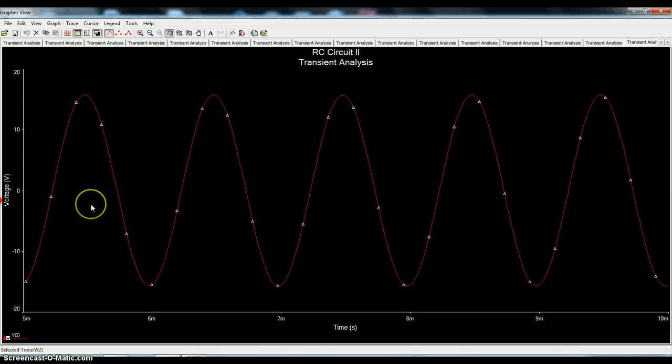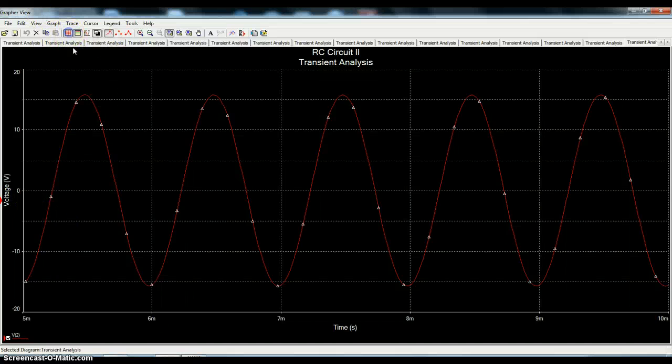And in fact, if we went back and used steady state AC analysis to calculate what the phase lag or lead, in this case it'd be a phase lag, of the voltage on the capacitor, you can actually probably assume this point to be equivalent to 0 because it's an integer number of cycles from the beginning, and you see that there is a phase lag of the output voltage. So this illustrates the process involved with a waveform, in this case a sinusoid.